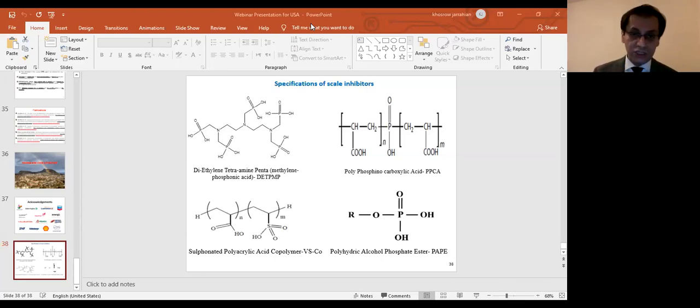And the second question is, what are the current challenges in scale inhibitors? Good question. Today I was presenting scale inhibitor squeeze treatment in carbonates. In industry, they haven't been convinced that precipitation can increase the squeeze lifetime because of induced formation damage in some cases.